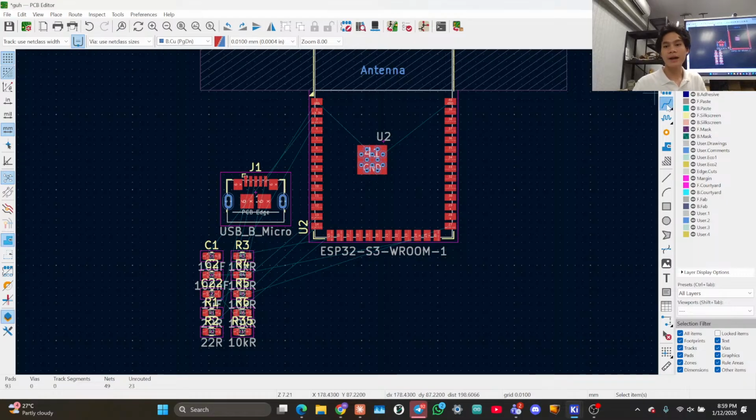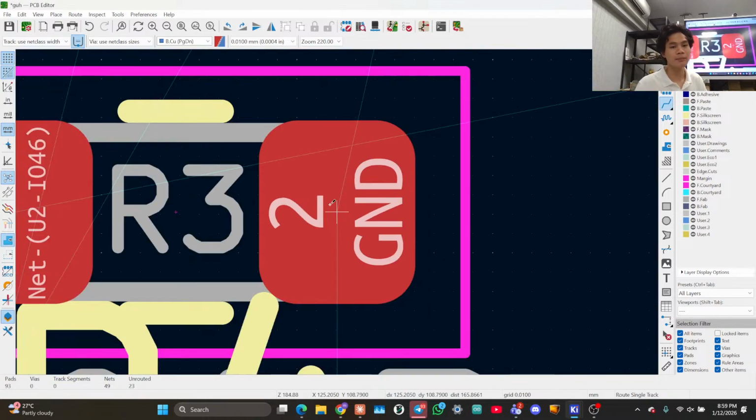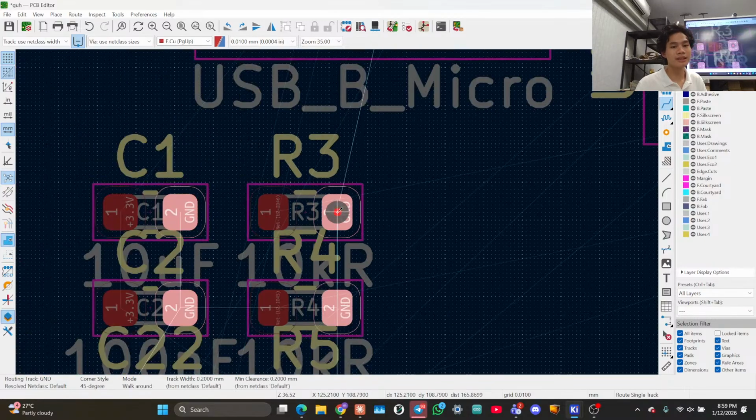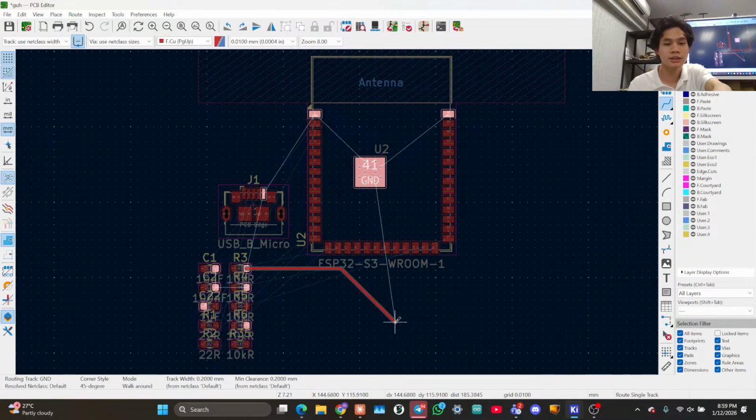So I can click the trace button, and I can try to wire two things together. This is a ground pin. See, it's labeled ground. So I can click this and just move my cursor out, and it will try to drag wires to it. Now check it out. Look at this. All of these have been highlighted because they're all part of the same net.